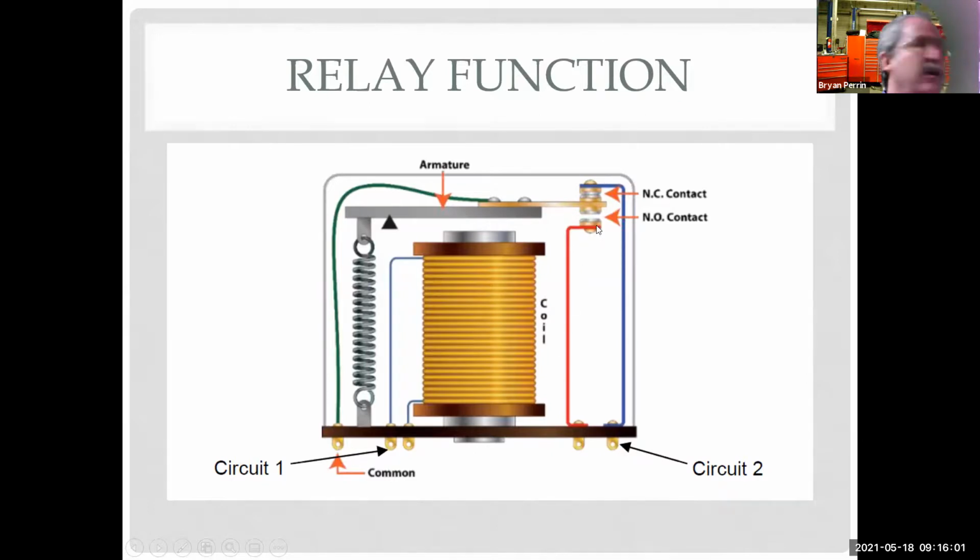The reason for that is the original relays all came 5-pin, but most circuits didn't use this blue part here for the normally closed contact. So they came out and made a cheaper 4-pin relay, and now there are several different kinds of relays and some solid state ones. But 87A is the default.